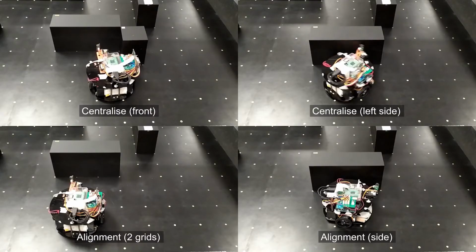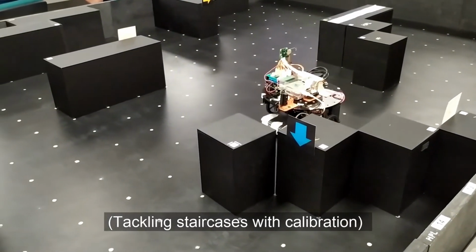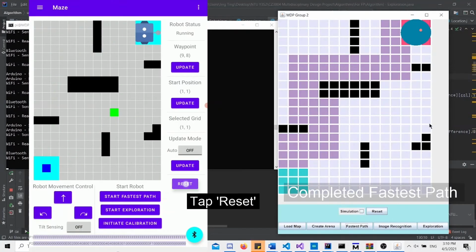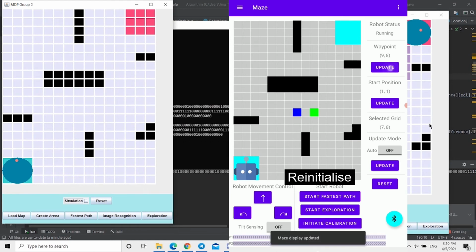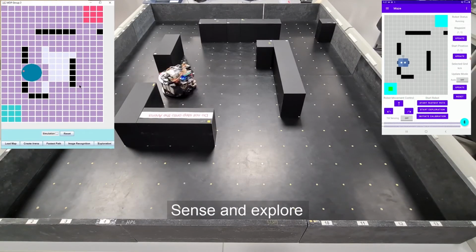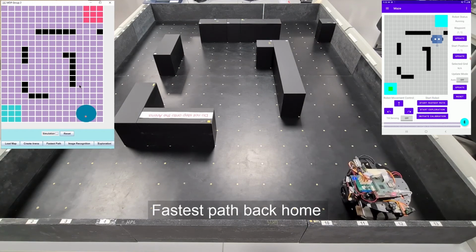We had to do regular calibrations, and we implemented a few algorithms to ensure that the robot does not crash into obstacles, and it can correct itself after avoiding obstacles. We implemented a reset functionality where the program does not have to be stopped or killed if we want to run the robot again. To tackle any unexplored areas during exploration, the fastest path algorithm is used to ensure we get all 300 grids explored, before using the fastest path again back to the starting location.